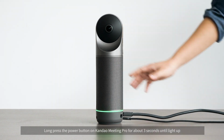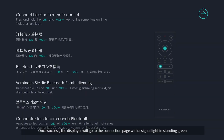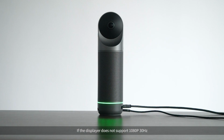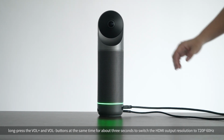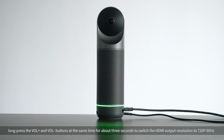Long press the power button on Kandao Meeting Pro for about 3 seconds until it lights up. Once successful, the displayer will go to the connection page with a signal light in standing green. If the displayer does not support 1080p 30 Hz, long press the volume up and volume down buttons at the same time for about 3 seconds to switch the HDMI output resolution to 720p 60 Hz.